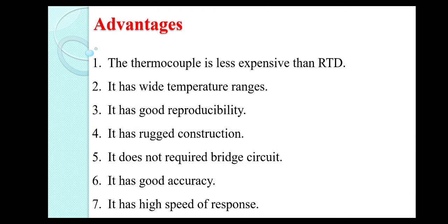Next are the advantages of thermocouple. First, the thermocouple is less expensive than the RTD. Second, it has a wide temperature range. Next, it has good reproducibility. Next, it has rugged construction. Next, it does not require a bridge circuit. Next, it has good accuracy and a high speed of response. There are several advantages of thermocouple. So instead of RTD, thermistor and thermometer, you can use the thermocouple.